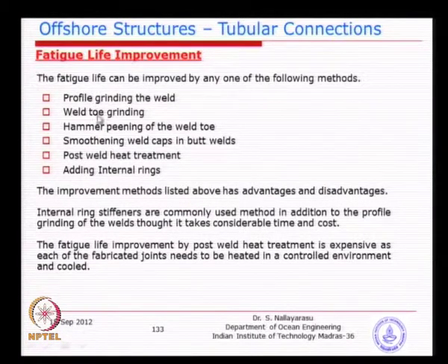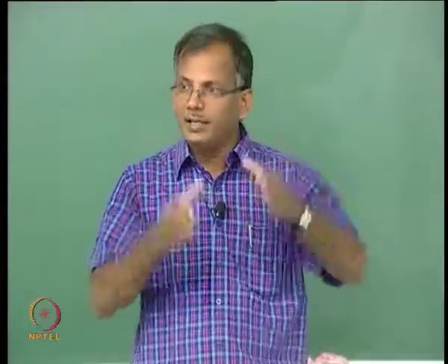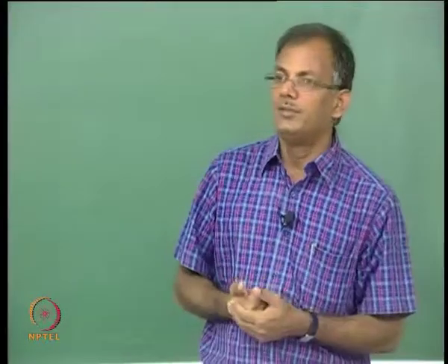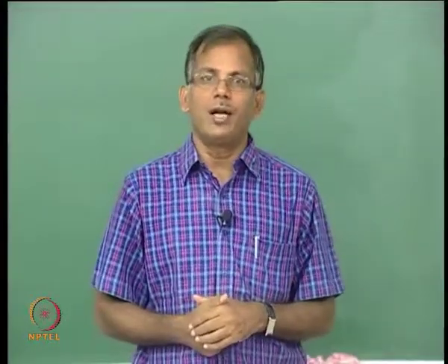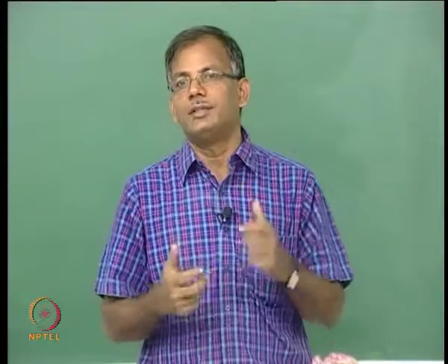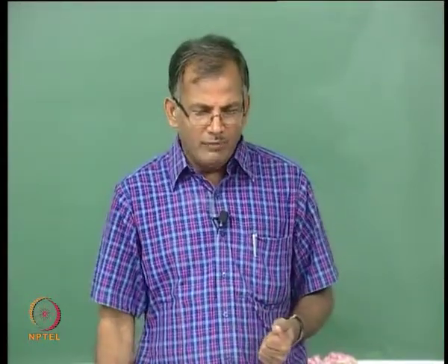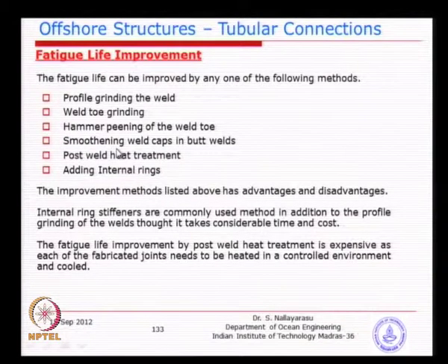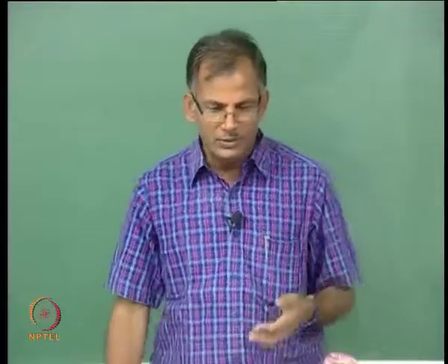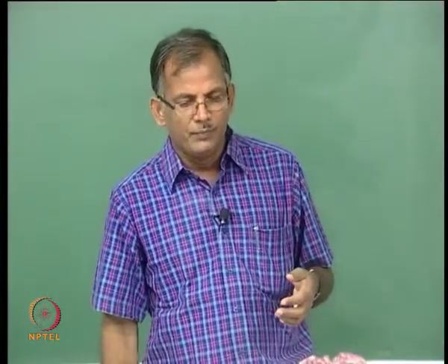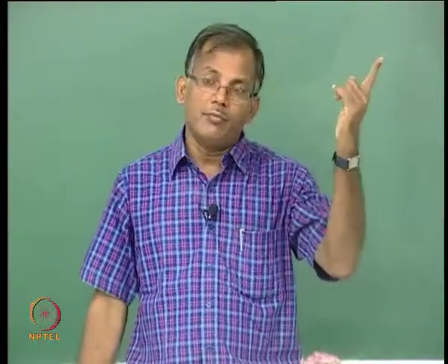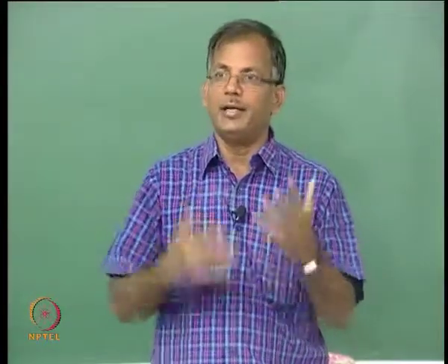Some of the ideas is providing rings. For example, we just learned that by providing rings you are reducing the stress concentration factor, but if you have a jacket leg with a pile inside, can you provide rings? We cannot. If you provide rings, you cannot do the piles. That is exactly the problem. So, all other ways of doing it are external, something to do with the connection between the brace and the leg. That is what we are going to see: how we can improve the design life and reduce the fatigue damage. So, that is the idea.